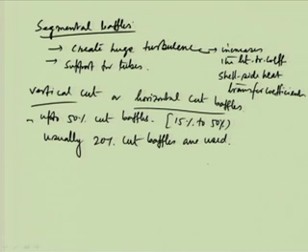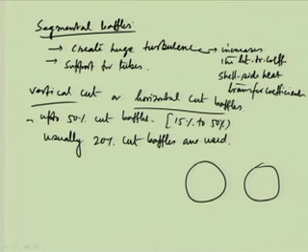So, if you try to see, when you have a baffle like this, this is almost the dimension of the shell. Now, what is happening? We will cut it. So, this part. This cutting can be like this. In that case it is roughly 15% cut or 20% cut. This cut can be on both sides. So, that means you have the tubes like this. Here the tubes are placed. This is a square pitch arrangement, you can understand from there. It can be triangular pitch also. So, this is one cut, this is another side cut. These are called horizontal cuts.